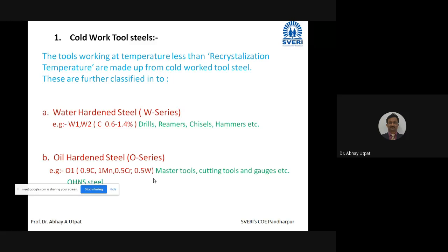So part is made hard either by forming the hard phase, martensite. I have taken the name in previous class. So ferrite, pearlite, and ledeburite, cementite. All these phases are present on the Fe-Fe3C diagram, but two more phases are not present.